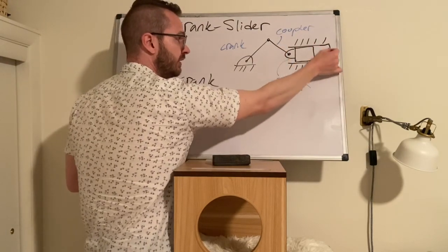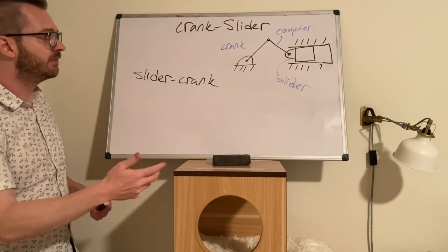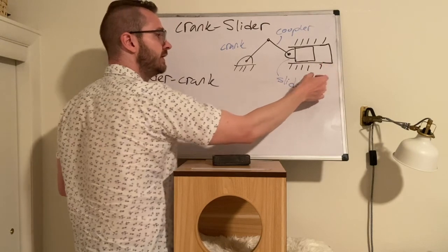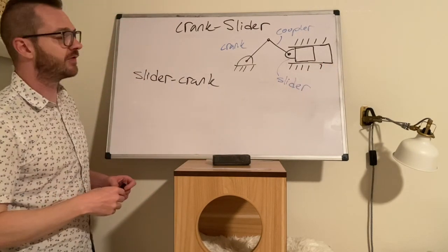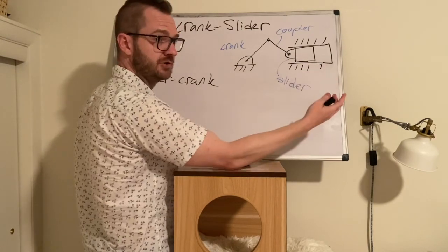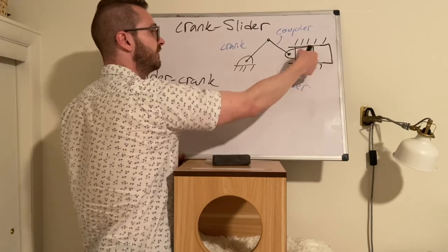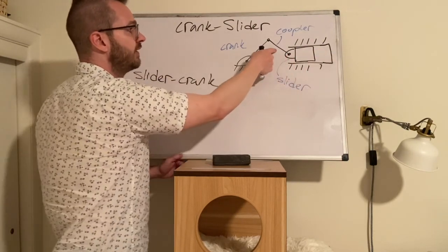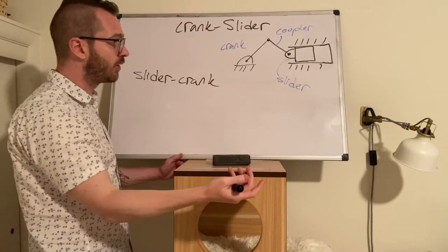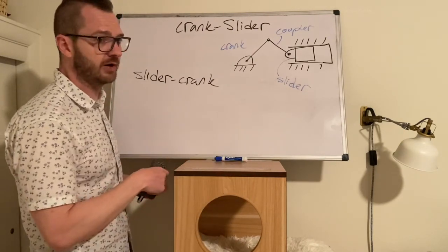It's going to drastically reduce this volume. You're going to spark it. The fuel will combust. The high pressure gas is going to be generated. The oxygen and fuel get converted into CO2 and water. You're left over with basically hot nitrogen, and that's going to expand rapidly. It's going to push against this thing. So this slider moves out. That makes the coupler move, and then that's going to force the crank to turn, and that is the output shaft of your engine. And then it goes through transmission, drivetrain, etc.